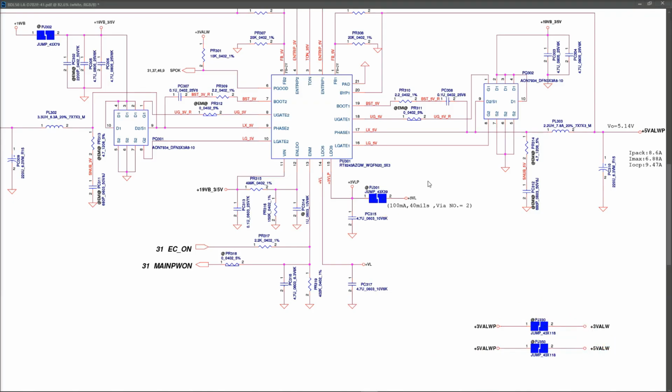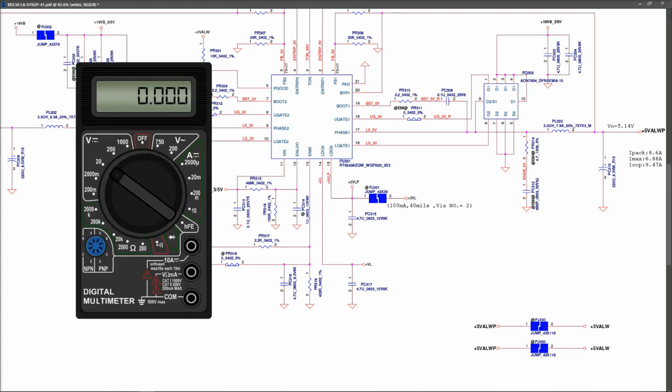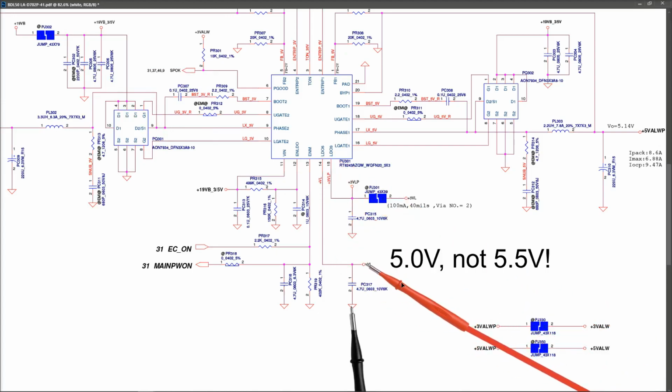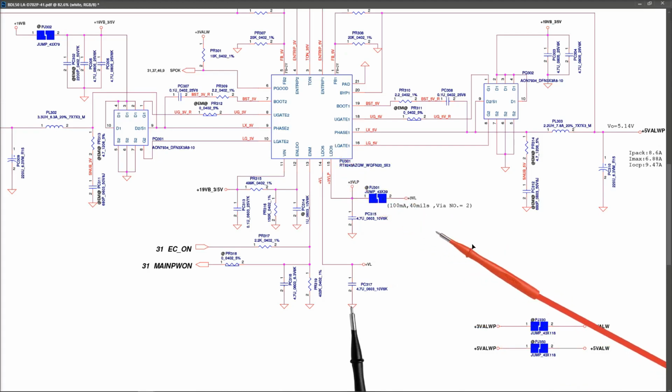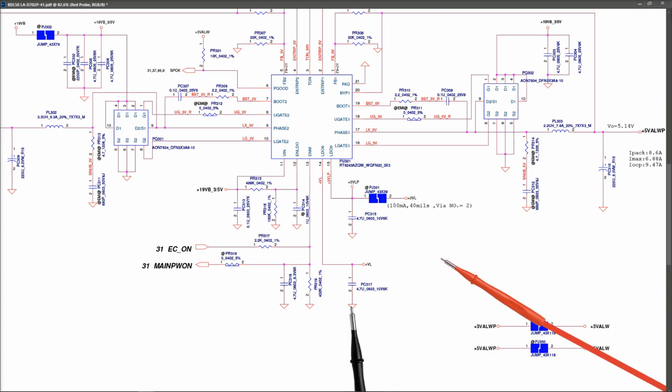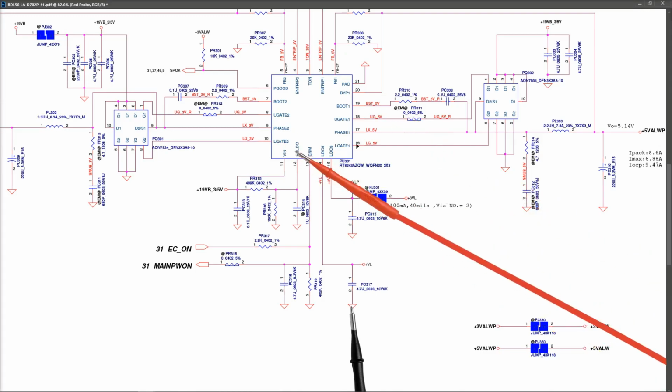So with confirmation that pins 14 and 15 were the pins of interest at this point, I asked him to introduce his multimeter in voltage mode, DC, place a black probe to ground and just take the two measurements. First of all of pin 14, and he measured 5.5 volts at this point, and then pin 15 and he measured 3.3 volts at this point. So we could be sure that there was confirmation that the two always on voltages were present and that this IC was doing its job.